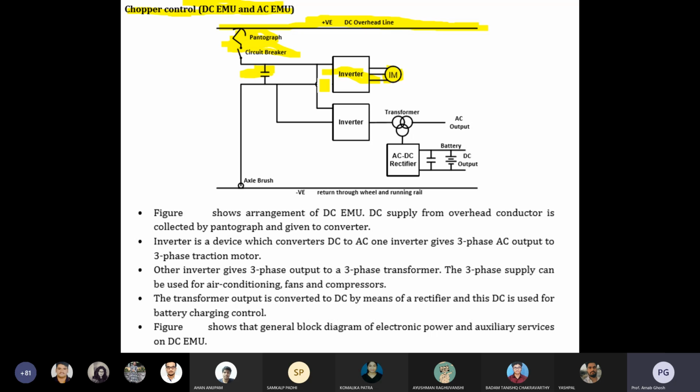An inverter can control the speed of the motor. You know the space vector concepts, so more sophisticated control of the speed of your motor. So you can also use an induction motor. With DQ control, you are converting ABC to DQ for smooth control of your induction motor.